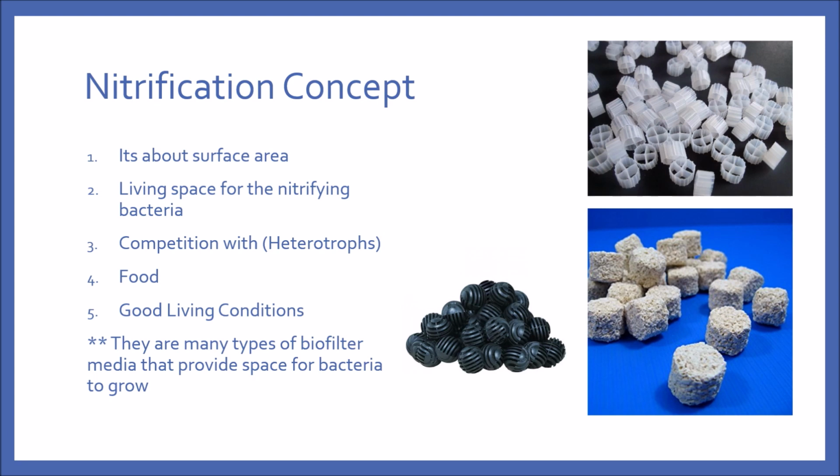Note that there are a lot of terminologies for the same thing. A nitrifying reactor or a biological reactor is simply where this process takes place. An important concept about nitrification is to provide enough surface area for the bacteria to grow on. We also have to provide them with adequate food, good living conditions, and protect them against competition from other types of bacteria.